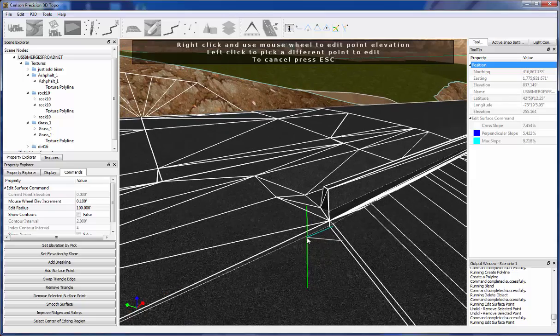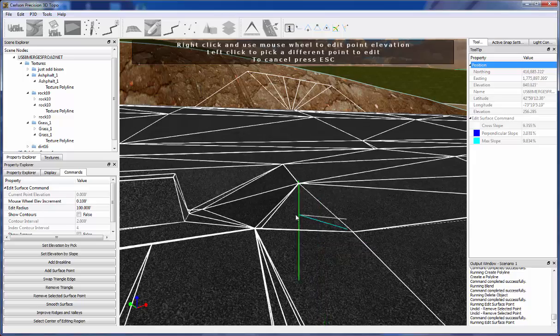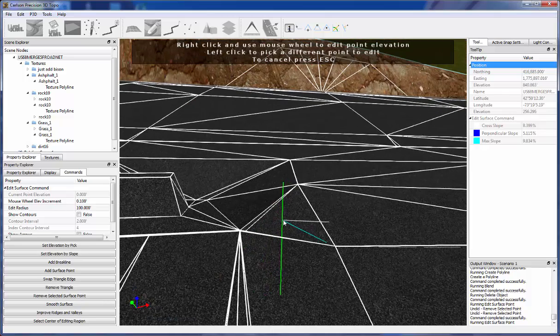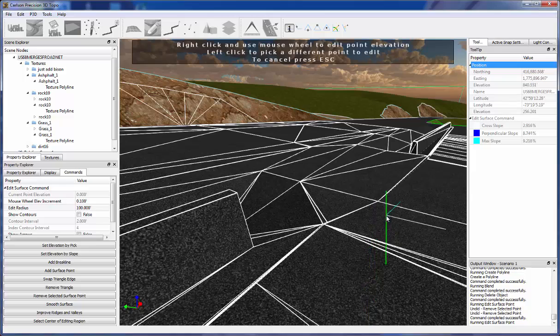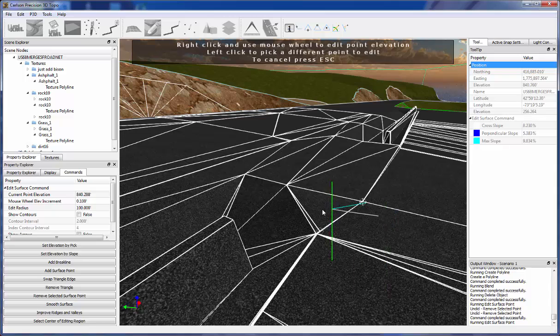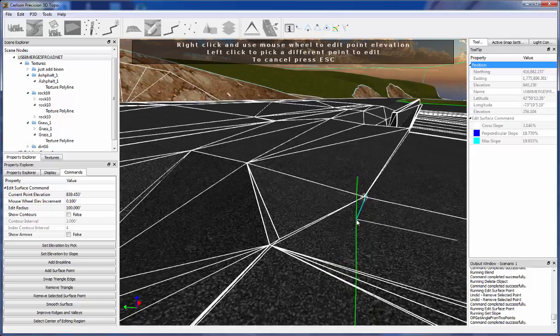But we still have a problem because the driveway is wanting to basically be very car unfriendly. So we can imagine the driveway coming in this way, where our ditch line actually starts in here. And this point looks a little bit low. So what I'm going to do is select that point or points, and I'm going to set the elevation by slope. And what I'm going to do is pick on an exemplar area where I want it to match the slope to.